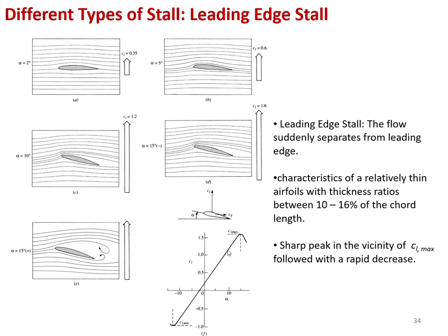So there is no gradual arrival at the stall condition, no gradual decrease in the CL. You can see that the CL is increasing linearly until it reaches the stall point, which is not the case for the other types of stall. So this is the peak, as you can see.